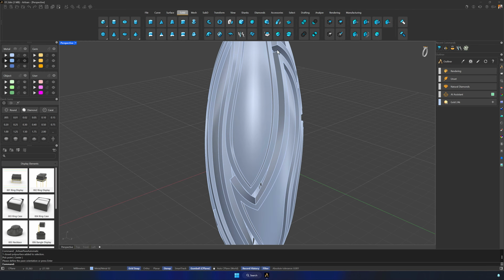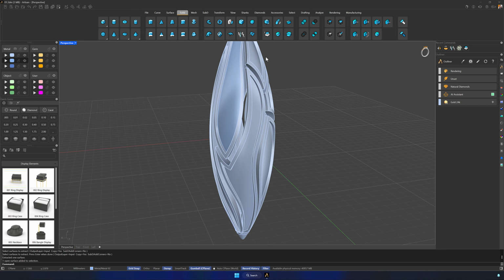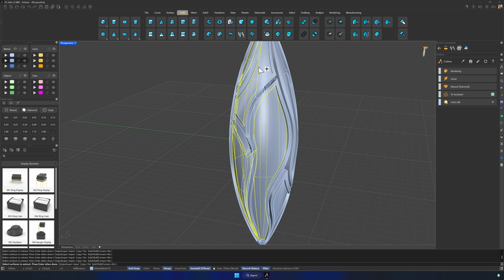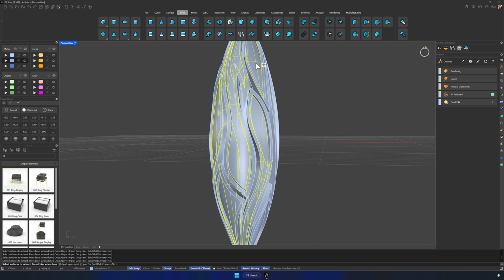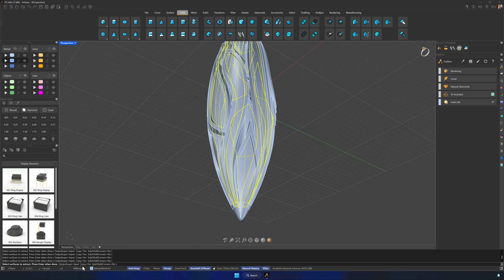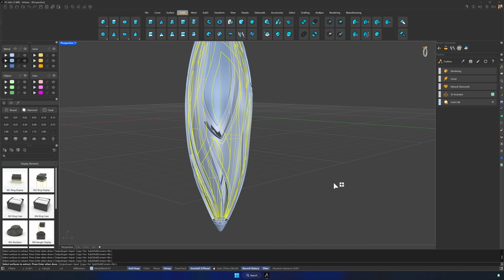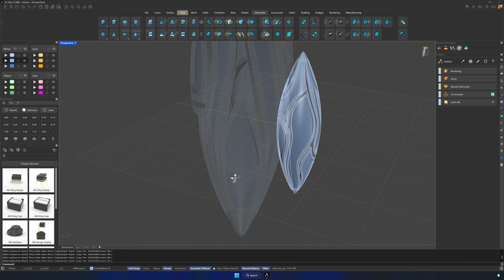But a better workflow is to first extract the surfaces we want to work on. We can change them to a separate layer, so they're easy to identify. I'll do this for all the areas where we want gemstones. Make sure Copy is set to Yes, because we don't want to modify the original solid. Right-click to confirm. Move them to a different layer. And now we can start. Now we can begin adding gems.